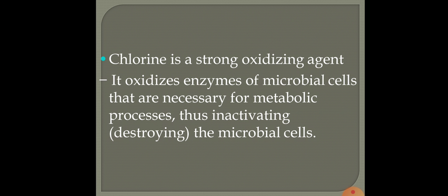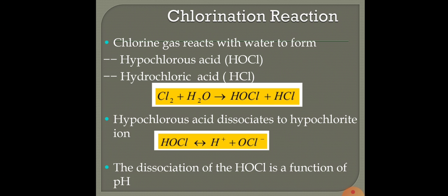As per this theory, the chlorine compounds formed when chlorine is added to water will interfere with certain enzymes in the bacterial cells which are vital for the support of life, and the enzymes involved are created within the cell plasm, and hence the action of disinfection proceeds in two steps. Firstly, the penetration of the cell wall by the disinfectant, and secondly, its reaction with the enzymes.